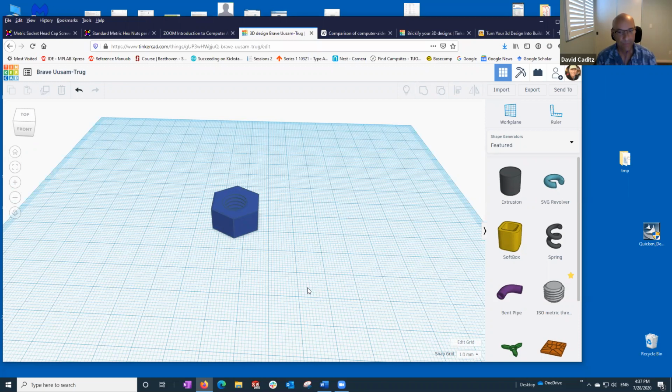So, all right, important concepts are the work plane, the primitive bodies or primitive objects on the right panel, and then the operations of combining things. Sometimes you turn something into a hole before you combine it, and it makes a hole instead of adding the solids together.